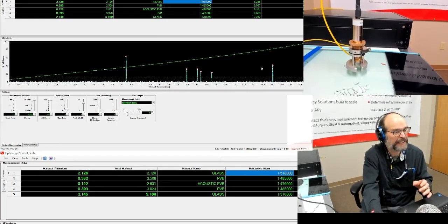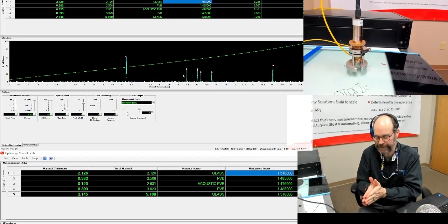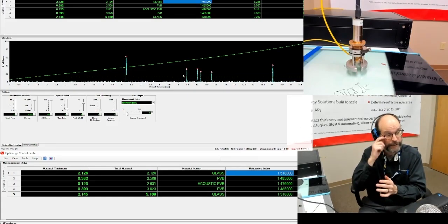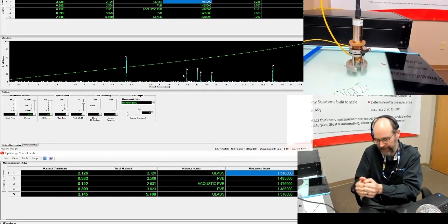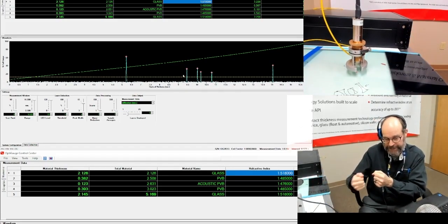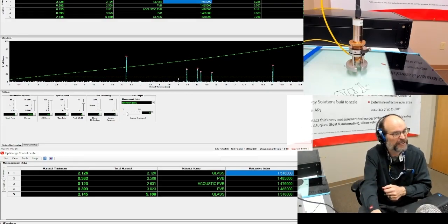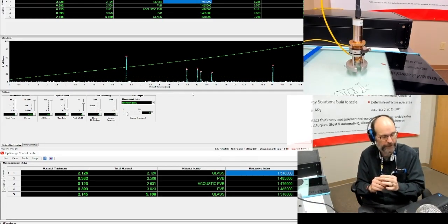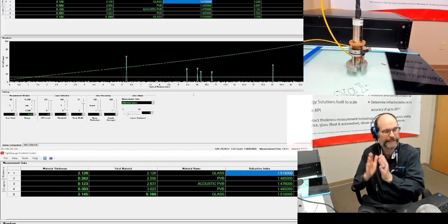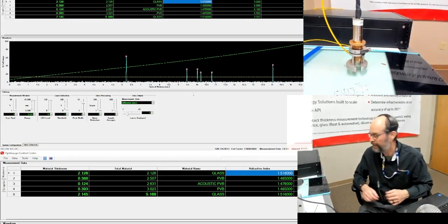What happens is there's an ideal location to get these inner peaks, right? The inner peaks have less light coming back because the index is not as dramatically different. So there's a height where the focus of the probe and the interferometer's sensitivity match, and it's usually around this area of the scan, and that's what you're trying to find. Where do those inner peaks come up the highest when you adjust the brass ring there?